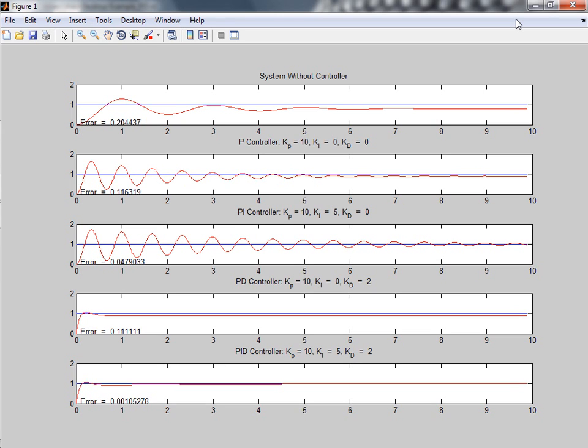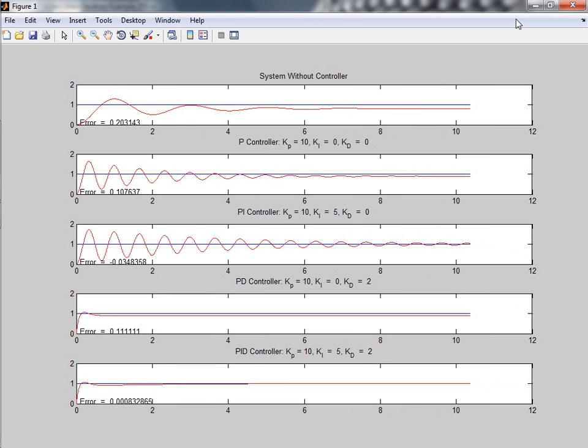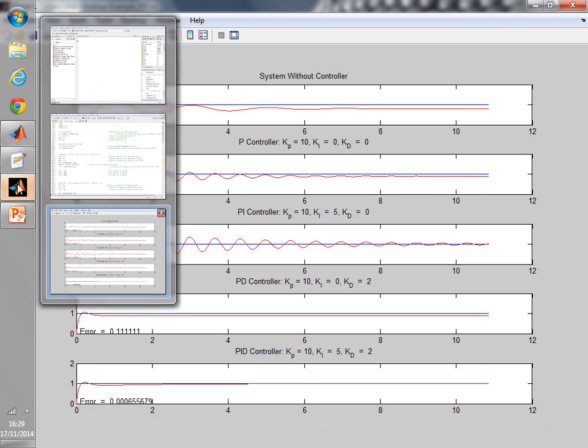If I want to improve steady state error, increase the damping ratio, reduce the oscillation, and improve the rising time, I use the PID controller. Look, the overshoot is almost 0, steady state error is 0, very fast rising time, and that's it. This is all I wanted. This is slow, so I can't run the other types of inputs, but please try this MATLAB code for the sinusoid input, sawtooth input, ramp input, or any other type of input, to see how the PID controller can improve the overall response of the system.